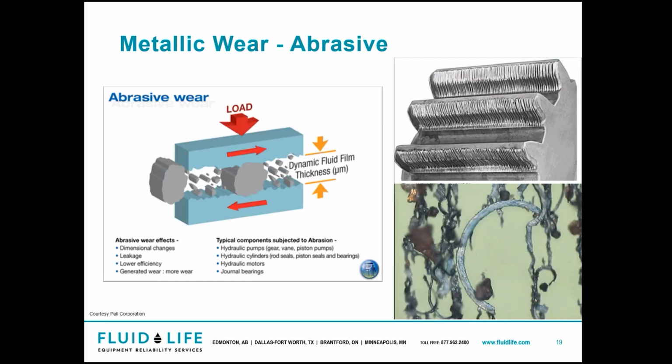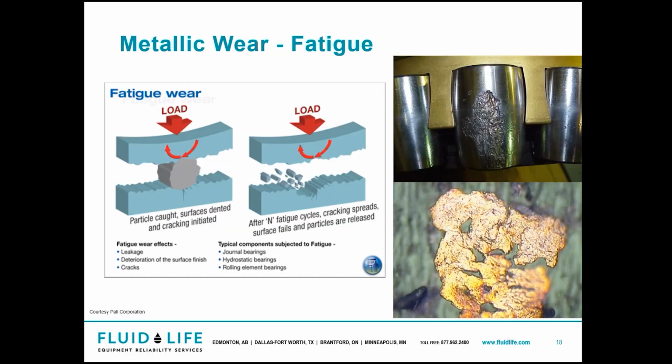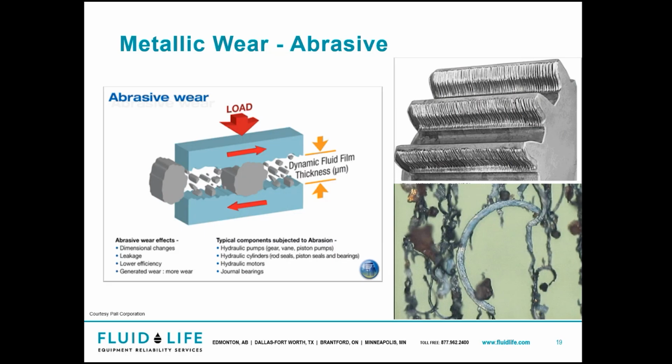Abrasion wear, so scoring, scratching, any of those kinds of removal or plowing of material. It kind of looks like metal swarf here, right, like you find on a machine shop floor. Again, these particles are a few micron in length, so far smaller than what you're going to see. Now, you know they're small particles, but these photos are taken at high magnification, and we see there's clearly some significant wear occurring.